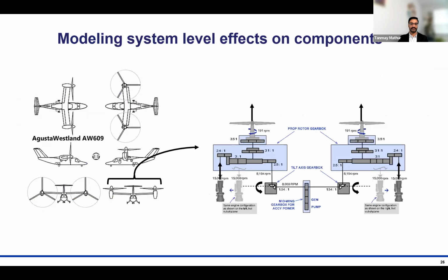So one such effort that we have recently undertaken is to understand how torsional dynamics of the drive system of a tilt-rotor aircraft affect the loads at the component level. Meaning, what should be the dynamic factor we must use while we are designing these individual component gearboxes.